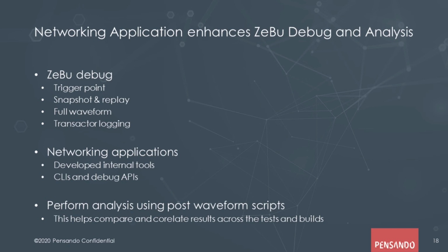Along with that, we also develop our internal tools, and as I mentioned, that was useful post-silicon also, and we keep enhancing this. This is application specific, and we keep developing them. We develop some tools that are ZeBu specific, where they dump the waveform and we post-process the waveforms. When we post-process a waveform, some sanity checks and performance and latency numbers are already extracted by our internal tools. That was very useful, because every designer needs to know these parameters upfront, so that a lot of issues are straightened out right there.